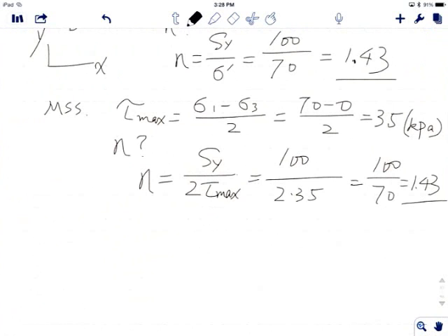this is what we did, and like you see over here, you have two different criteria to determine the failure, and we know design safety factor is nothing but just a measure of the failure stress over the stress state you have, right? So when you use maximum shear stress, you are considering the shear stress, while for the distortion energy, you are considering the von Mises stress, which is the same one as what you output from your finite element analysis, right? Okay, so that's that.